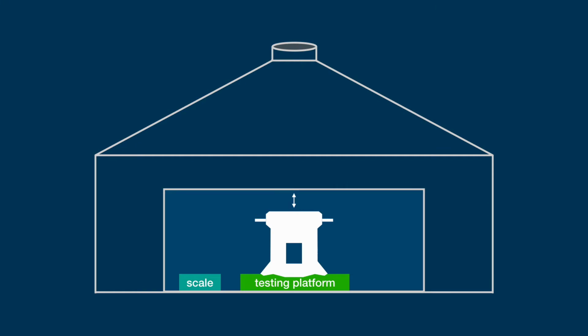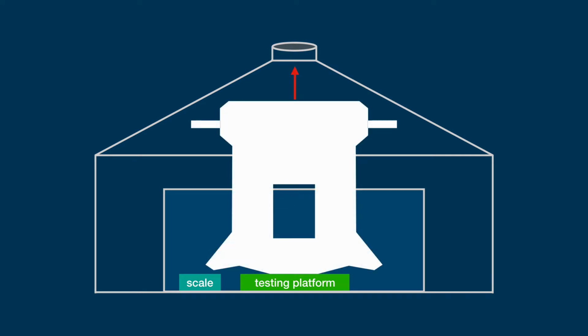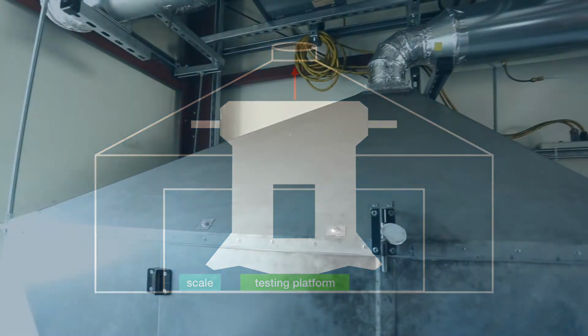We also recommend that exhaust leave the cookstove into the hood's widest section. We do not want the suction from the duct to pull air through the cookstove and draft it. You can see in this extreme example, a very tall cookstove may approach the narrow section at the top of the hood, leading to draft. We want to avoid this situation.